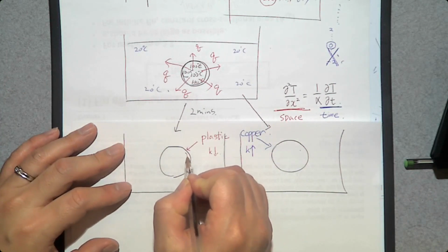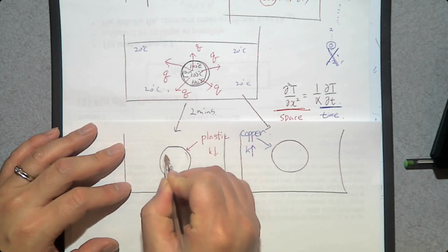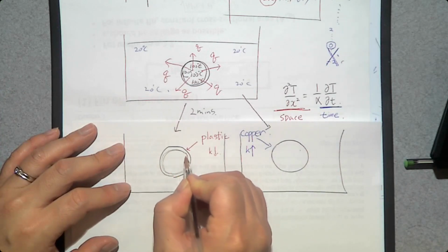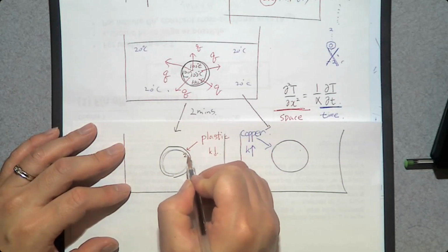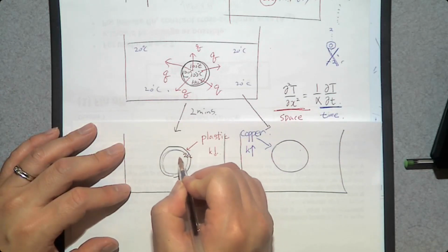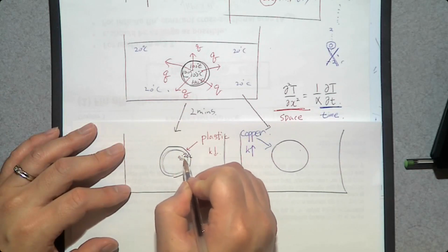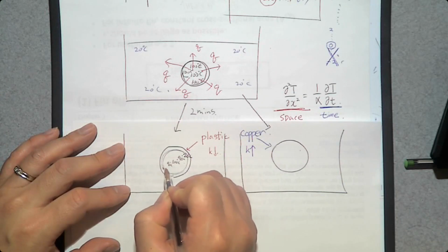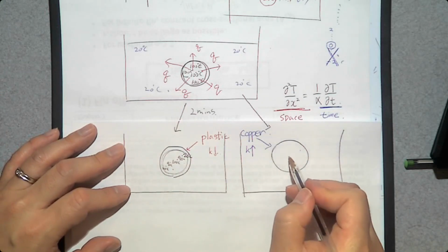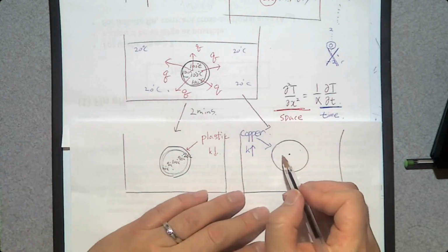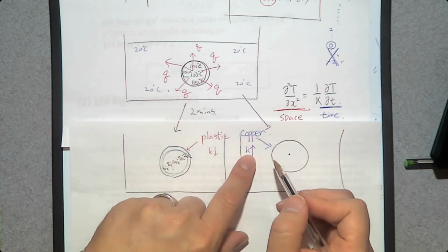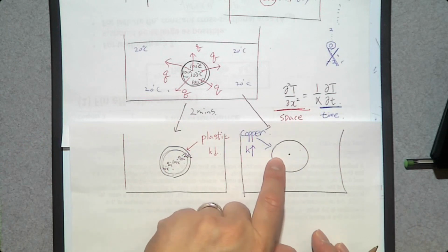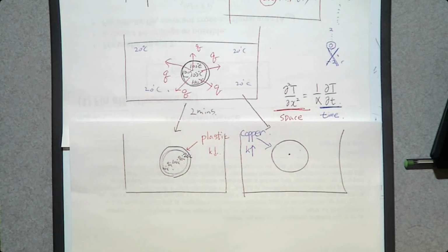Initially, the temperature near the surface will drop first. So here is going to be 20, away from the surface still 90, at the center 100, 90 and 20. On the other hand, in this copper block, the thermal conductivity is pretty high, so the heat transfer from the center to the surface is going to be extremely fast.